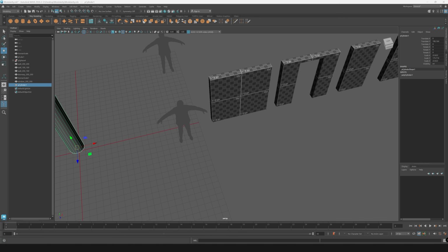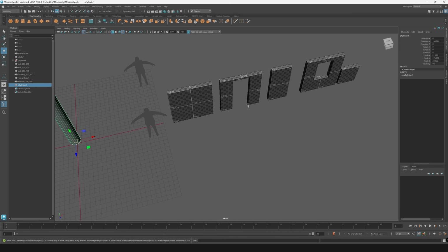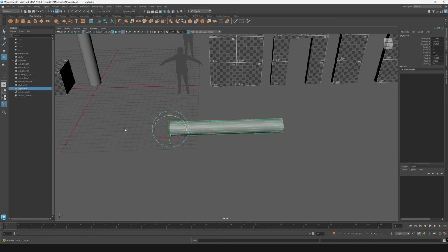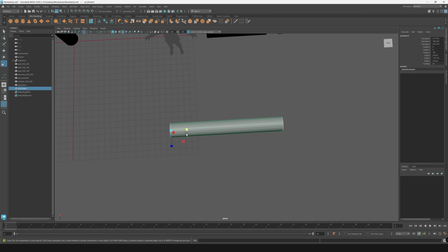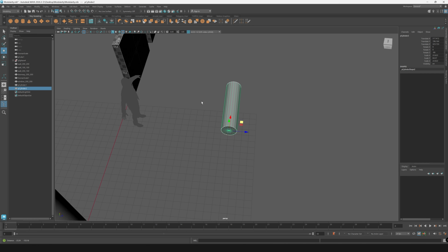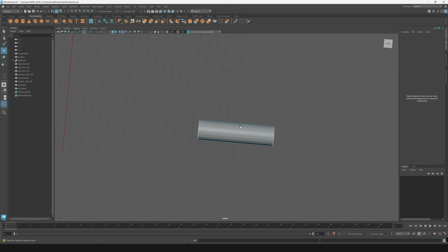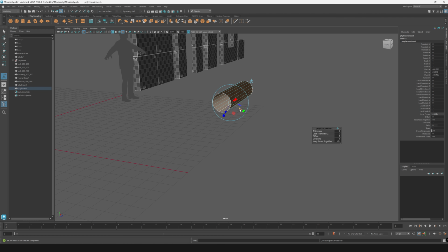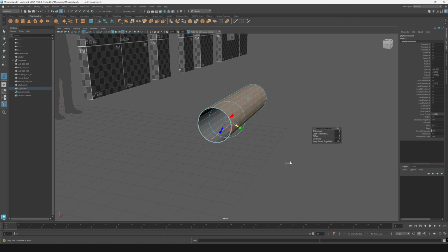The last thing I want to go over on the hard surface side of things is some basic props, like pipes. Just like we talked about with the columns, you probably want to rotate this guy like so, and we'll use him as my example pipe. Let's make a little segment here, and quickly select these faces, hold shift, select again so I can do an inverse selection, and delete the inside. Then let's do an extrusion, and I'll do an extrusion from the inside.